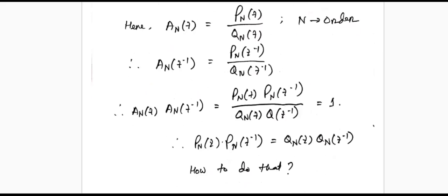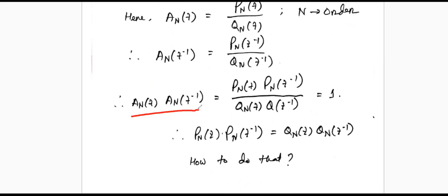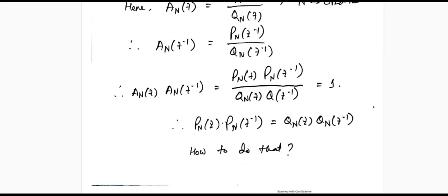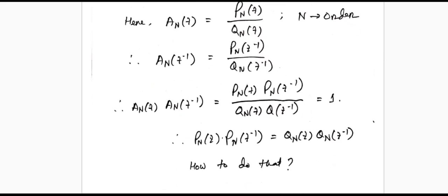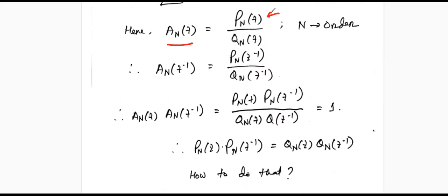Okay, now when we multiply these two, we already know that that is equal to 1, and now we have this pole-zero combination for these two functions, so that will of course produce this output. We need to know that for the all-pass filter, these are the zero locations and these show the pole locations. And for the inverse function, these are the zero locations and these are the pole locations.